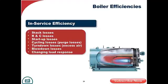Now, let's look at in-service efficiency. Well, the criteria for that: stack losses, radiation and convection losses. What are the startup losses? What do they mean? Cycling losses, which really result in purge losses. Turn-down losses, which is really, we're looking at excess air. And as I said before, most boilers, when they turn down, the excess air rises. What are the blowdown losses? And what is the changing load response? In other words, how effective is this boiler in reacting to load swing? So that's in-service efficiency criteria.